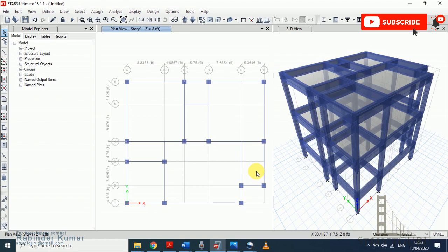So now, if concrete cracks after 400 psi, the moment of inertia will be reduced because of cracking. If the moment of inertia is reduced, the capacity of section to resist the bending is reduced. Its stiffness is reduced. The concrete will take less moments. Its deflection will increase due to less stiffness. So this moment, which the cracked beam is not taking anymore, will be redistributed to the other structural members based on their stiffness.